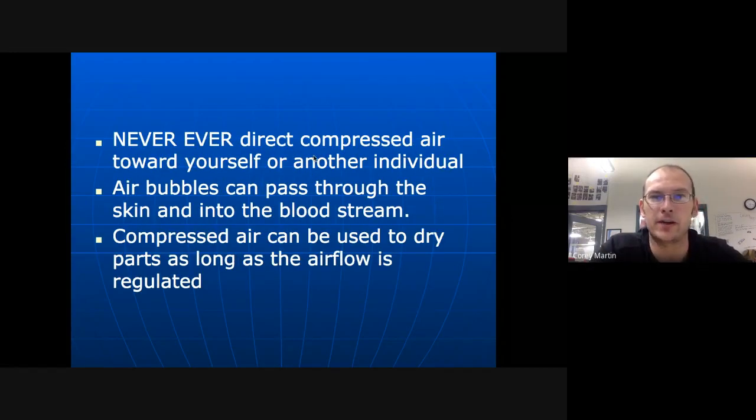Never, ever direct compressed air towards yourself or another individual. This is a big, big, big no-no. This is something that will get you thrown out of my shop. I will make you come sit in the classroom and you will not be welcome out there anymore. This is a big, big issue. It doesn't take very much air pressure to blow out somebody's eardrum or potentially make somebody go blind. There are a lot of dangers associated with compressed air.